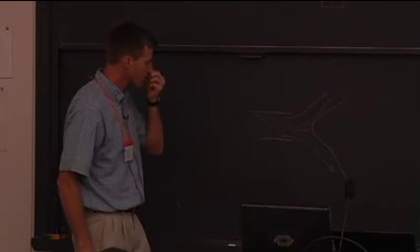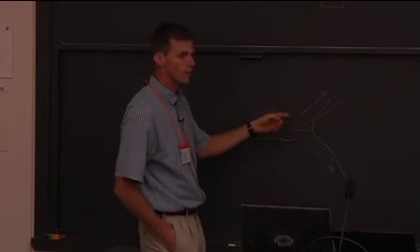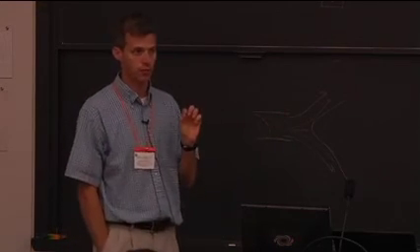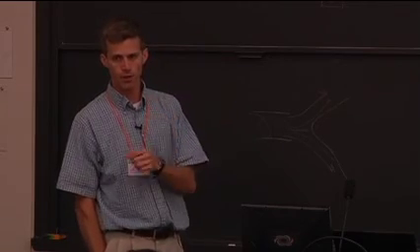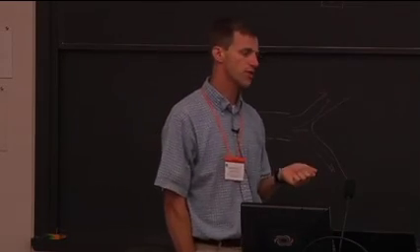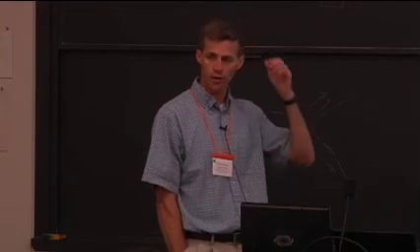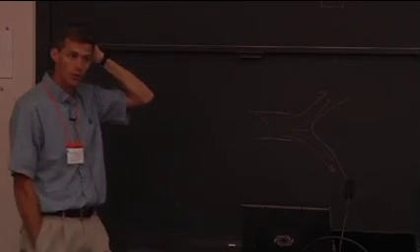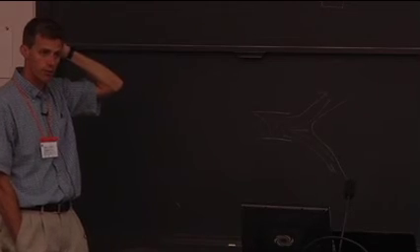One of the interesting things about a low swirl burner is you don't have vortex breakdown. As soon as you have vortex breakdown, you actually lose some stagnation pressure. And again, if you think about your cycles class, loss in stagnation pressure across the combustor does have a direct hit on cycle efficiency. So it's an interesting way of possibly stabilizing a flame with a lower stagnation pressure drop across the combustor.